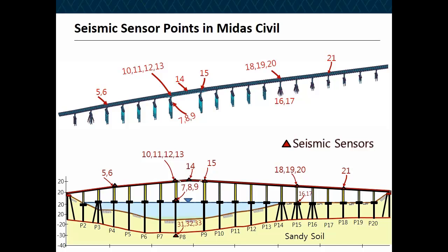If I look at the schematic of this diagram here, you can see some of the pile caps are buried into the soil. And then starting at Pier number 14, the piles are cantilevered above the mud line and support a massive pile cap. So when I do my analysis, any action that I should see are really in this zone, because most of this is very stiff, but here is where I have the cantilever, where I have massive structure, and all the actions should be happening in this zone.